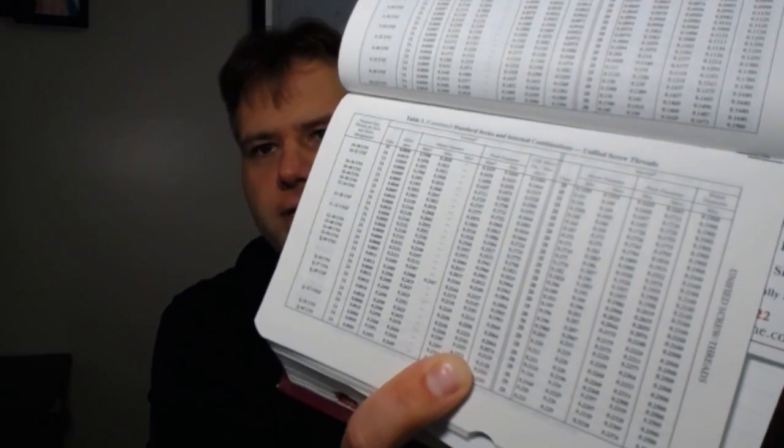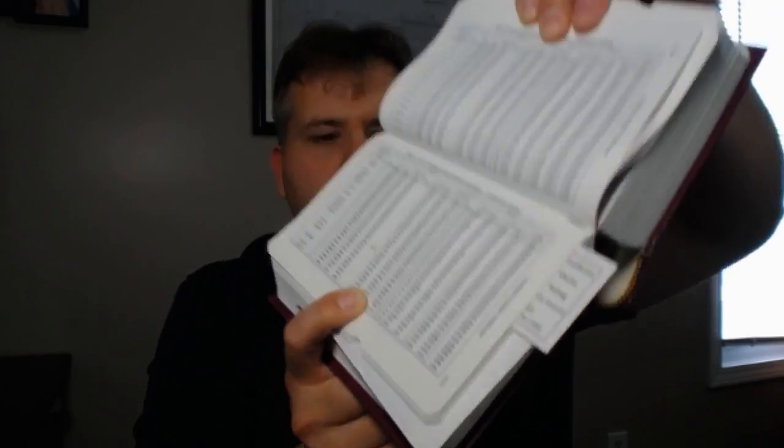Because one of the things we have to talk about when we are doing threads is tolerances. This is where my trusty machinist handbooks come in. I can show you how small the lettering is in here. It's extremely small, so you have to either get your own or trust me. A 1/4-20 thread actually has a tolerance on the diameter. So a 1/4-20 UNC, that's the one we have, and we picked a 3A. What was the gauge pin size, or the high accuracy one?